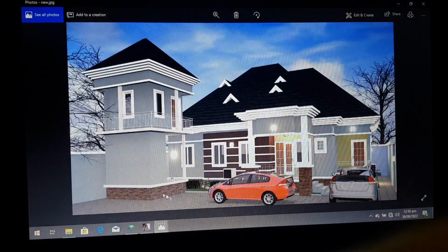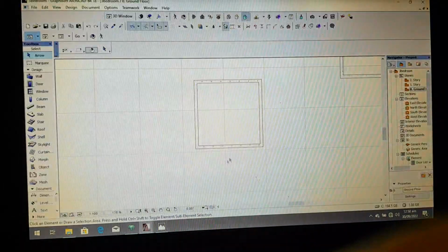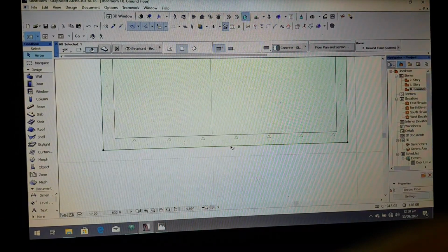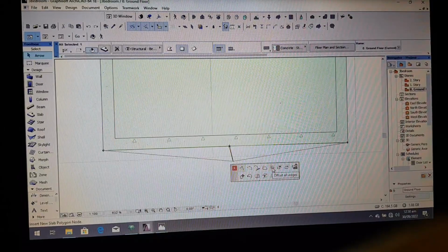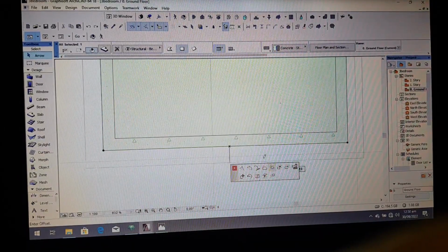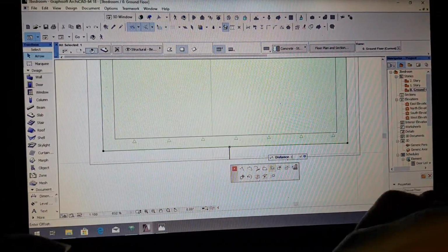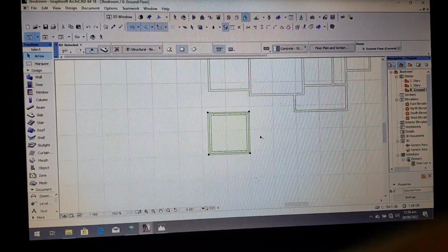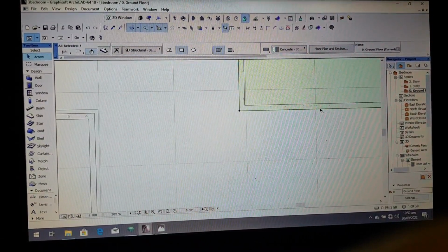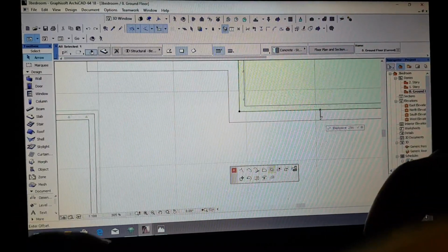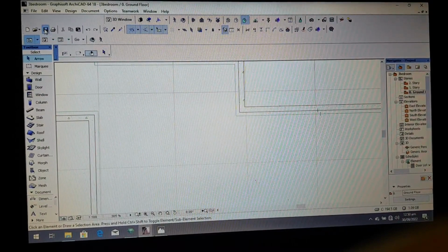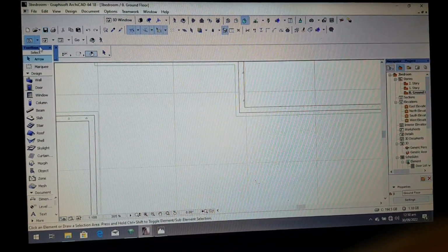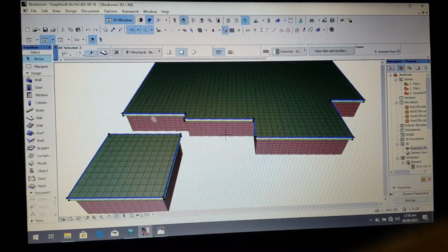Now look, there is a push out. This slab has a push out, so we're going to set out the push outs. So we'll come here, you click at this edge, you click on offset all edges, you type in 100, that's 4 inches. Then you come here, you do the same thing, offset of 4 edges. Okay, yeah, so you save. Always remember to save.